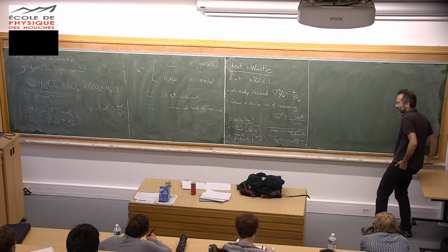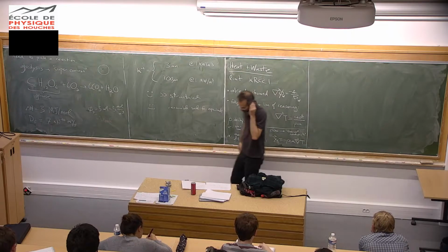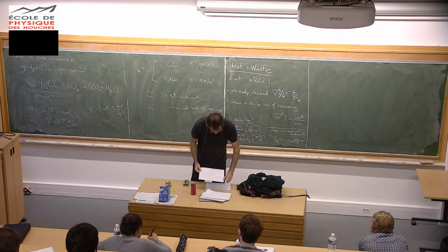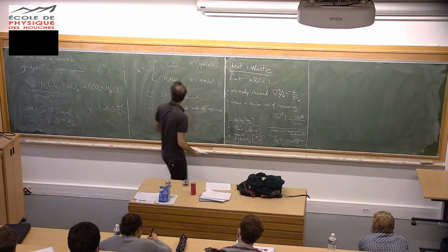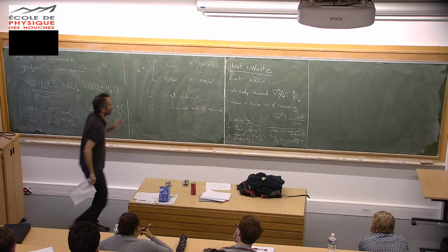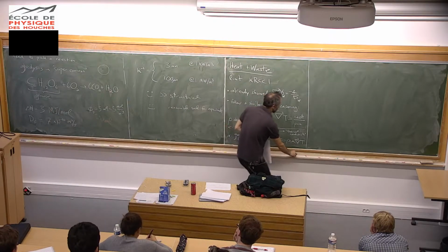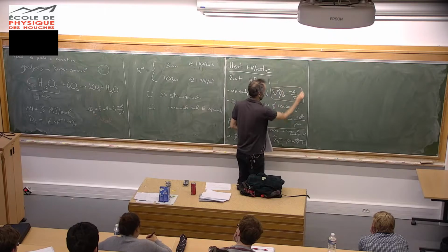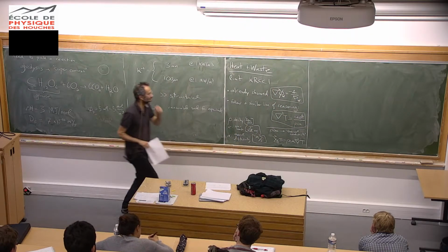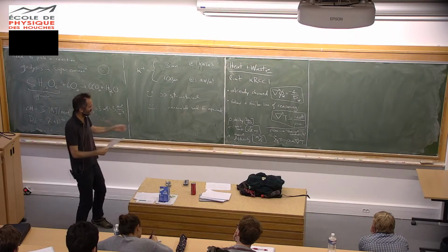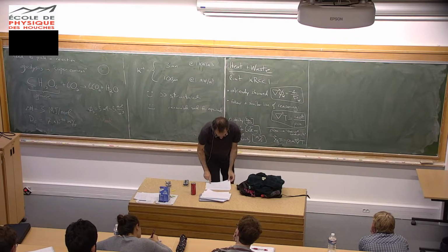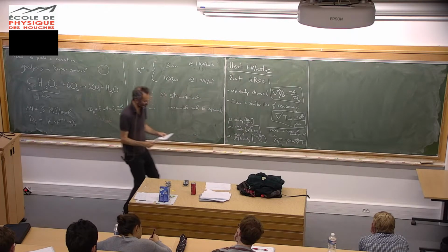Okay, so a really important thing to point out about these equations, in contrast to the governing equation which I erased for the fuel, is that these two equations don't have a length scale built into them, right? So they have a fundamentally different nature. And that's clear when you look at the solution.